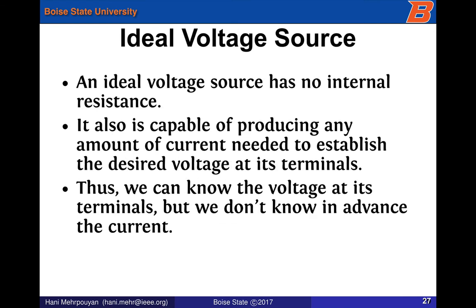So the other item that is important is an actual voltage source or power source. We have ideal voltage sources that we use, but there are also non-ideal sources. In an ideal voltage source, we assume that the terminal can maintain its voltage no matter what current we draw from that source. In reality, they don't exist, but on the circuit side, we can make such an assumption.